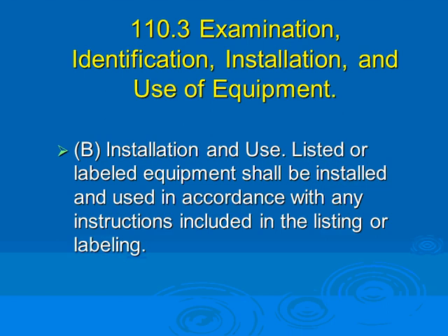Well, most of the people will say no, because the accessibility is related to most of the GFCI installed in dwelling and non-dwelling locations. Six feet from a sink, countertop in a kitchen, all of these have to be accessible. Now, if it's feeding a fountain, for example, a fountain has to be plugged into GFCI. Or if it's powering a vending machine, if you read it literally, it doesn't have to be, but look at the listing. They had this discussion with Sam there.